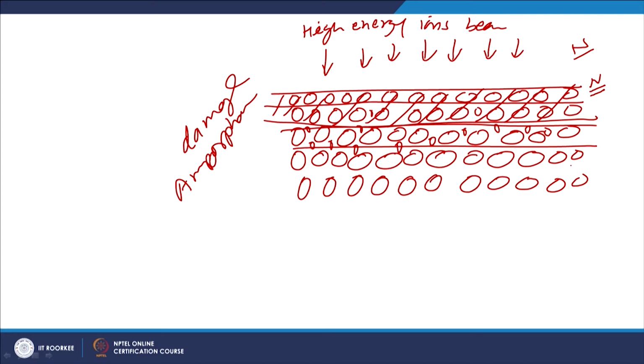chemical composition. So this is how we will be modifying the surface and near surface layers' characteristics by damaging the crystal structure, and by changing the composition by introducing particular elements. Nitrogen is one of the commonly used gases for introducing nitrogen ions in the metal, which after reaction with the iron especially forms the iron nitrides to improve the surface properties.